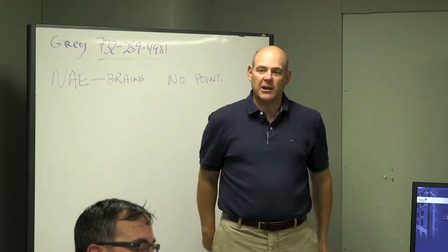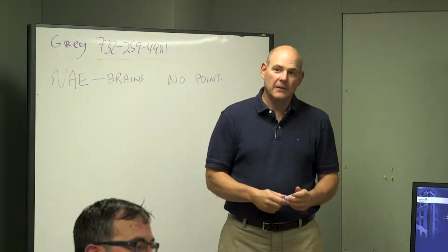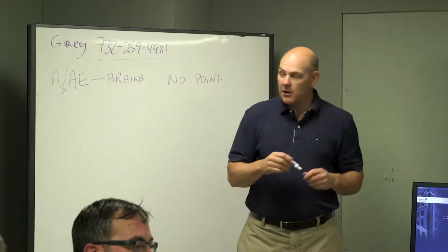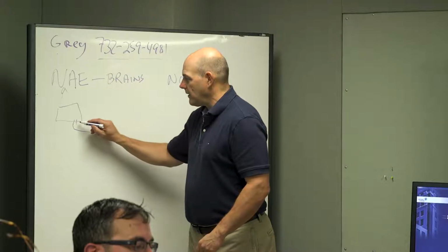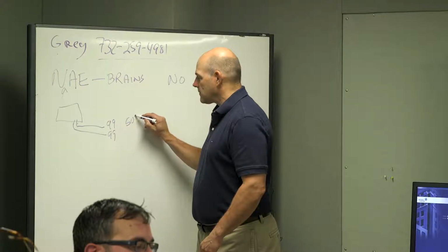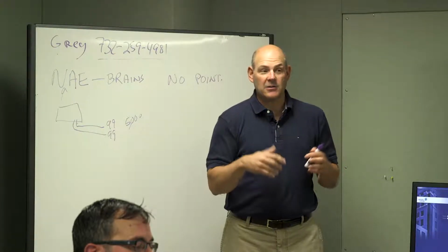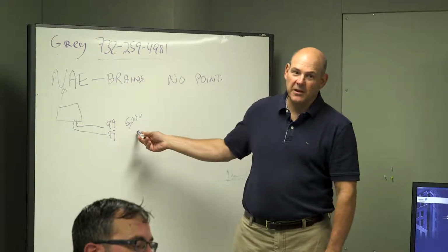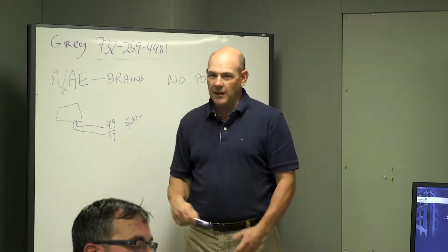So when you go onto a screen and you see, hey, I have 20 VAV boxes not reporting, the first place you want to troubleshoot is the NAE. Okay? So basically when you have a network riser, an NAE has 2 ports on it that can hold 99 devices each, or 5,000 points, point count. That's point count. So if you have a VFD and you're sucking in 30 points, you're not going to hit your 99 devices because your VFD is going to suck up a lot of data. So these are the things that can overload the NAE.